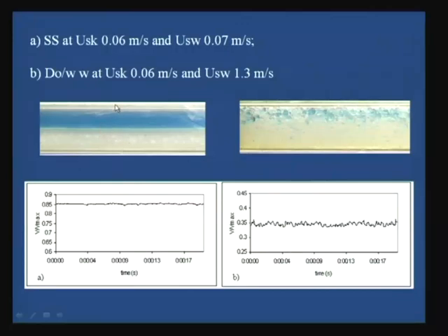Okay. So, you just see, when it was stratified flow, see here, large amount of kerosene is here, here small amount of kerosene is there. For a large amount of kerosene, we got a higher voltage value. Sorry, here less amount of water, large amount of kerosene, yeah, correct. So, therefore, we got a higher voltage value. Moment we had a larger amount of water, we had a lower voltage value.